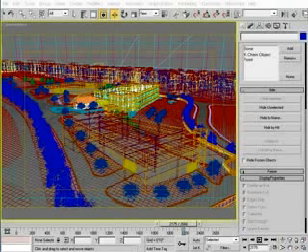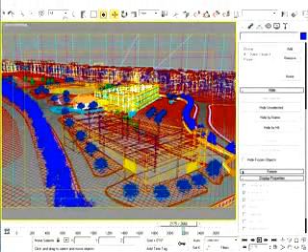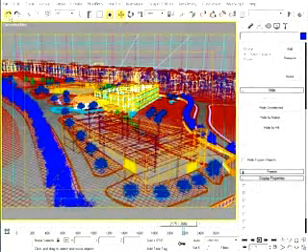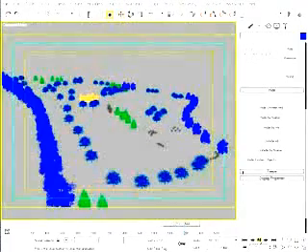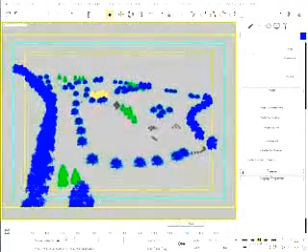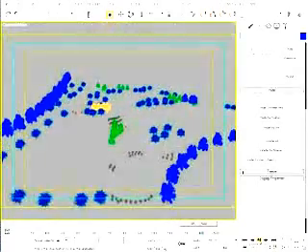Now let's look closer at exactly what a VRay proxy is, and it's one of my absolute favorite features in VRay, and I would recommend using VRay to users that don't know anything about it, if for no other reason than this one feature alone, because with this one feature you could literally render immense scenes with almost a limitless number of faces. A VRay proxy is a little bit like an external reference.